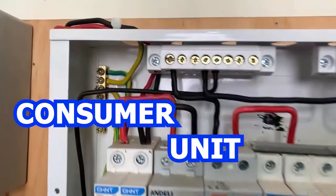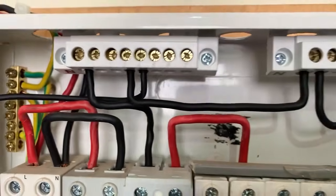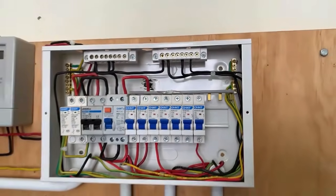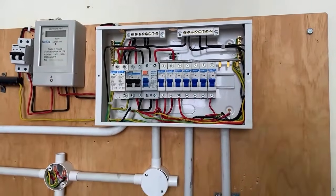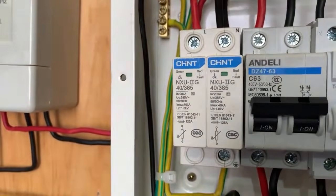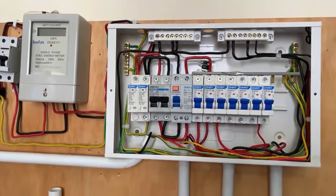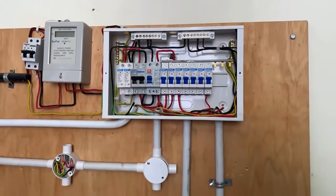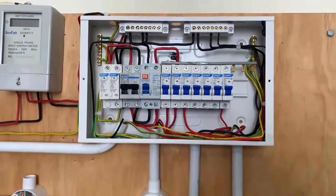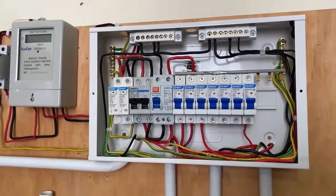In a consumer unit, we have very important features. First of all, we have the neutral bar or the neutral connect. What are some of the faults that are associated with loose connections on the neutral bar? We'll talk about that. But first of all, when it comes to MCBs, the protective devices that we have, for instance, this one, we have an SPD, surge protective device. We have the isolator, we also have the RCCB and the MCBs. Loose connections are the main issue that can occur in these MCCB or MCB connections here.